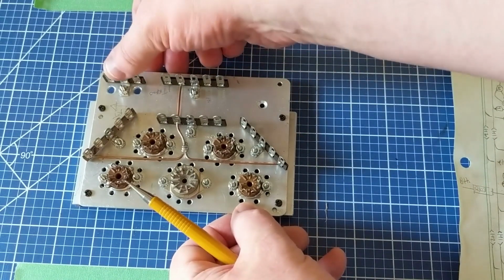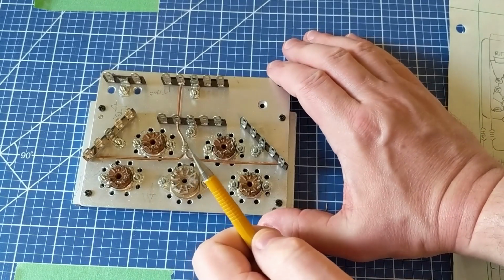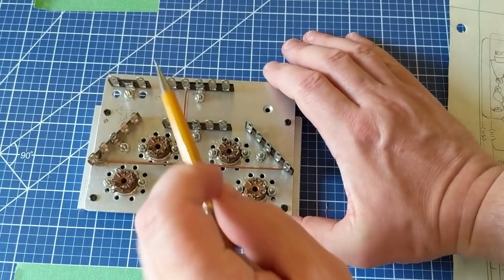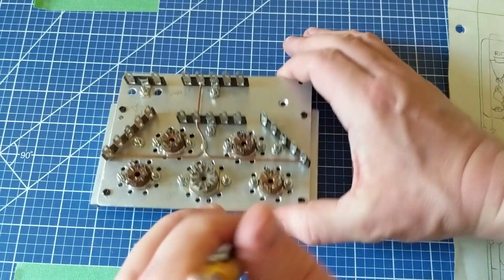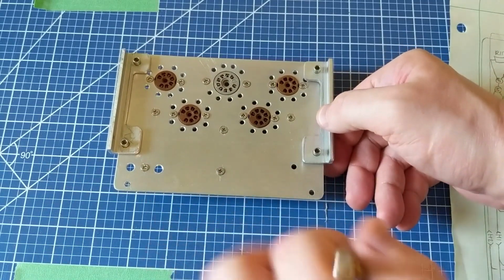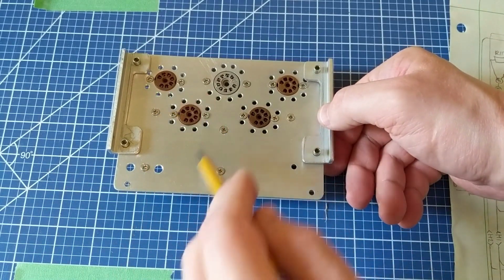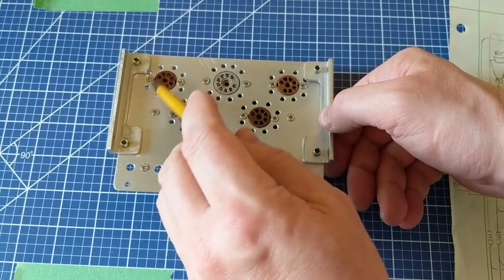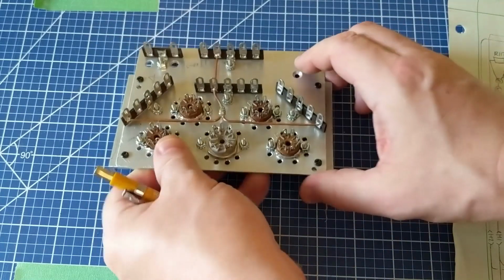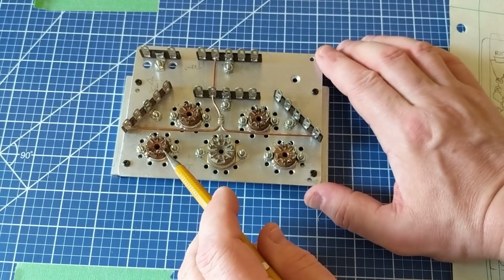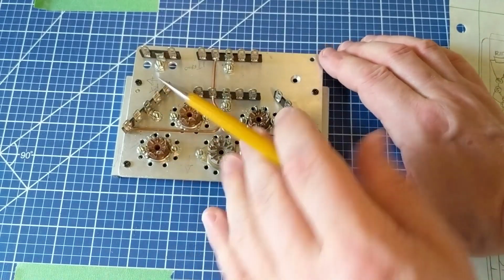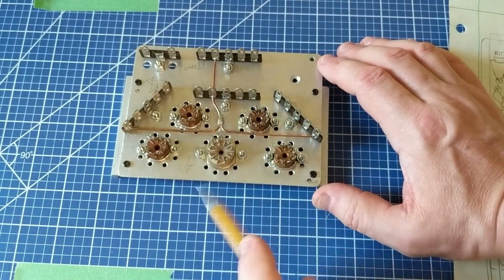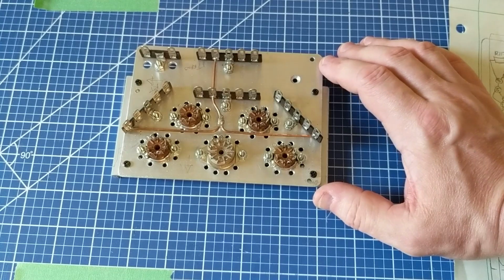This is where the heater is going to be coming in, and I'm going to try to minimize noise generated from the heater voltage wires by having them go through this hole here to the top of the chassis, and then route the wires on the top side of the plate to the appropriate places near the sockets, and then use these holes to have the wires go down and then tie into the socket on that side. In this way, I'm trying to separate the 6.3 volt AC line from the rest of the circuit, doing the audio to try and minimize noise.